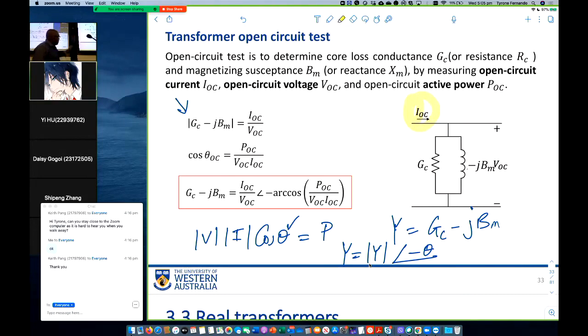And we have the conductance. We have the admittance. We represent the conductance and susceptance, right? Why do we represent the shunt branch as conductance and susceptance? Do you recall from my first lecture? Because when you have elements in parallel, it's convenient to think about conductance and susceptance, because you can simply add them, and that's the admittance, right?